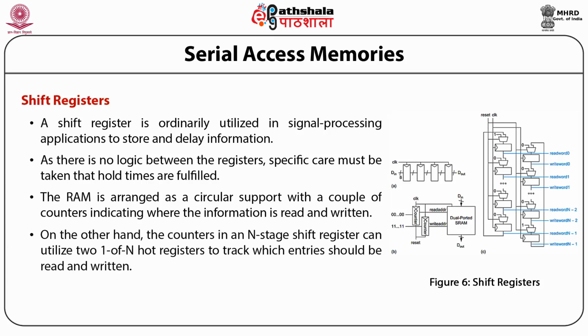On the other hand, the counters in the N-stage shift register can utilize two 1-of-N hot registers to track which entries should be read and written. Again, one is initialized to point to the first entry and the other to the last entry.